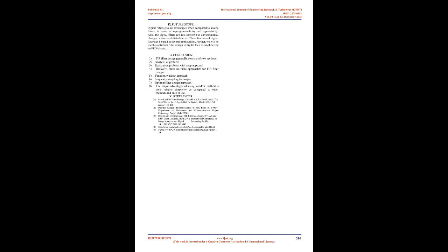7. Nexys 4 board, Artix-7 FPGA DDR board. The Nexys 4 board is a complete development platform based on the latest Artix-7 FPGA. The Nexys 4 board is compatible with Xilinx's family optimized for high-performance logic, and offers more capacity, higher performance, and more resources than earlier designs. In this project we required 15,850 logic slices, each having 6 LUTs and 8 flip-flops. Also, RAM of 4,800 kbits is required, and 240 DSP slices are used for reduced DSP utilization.